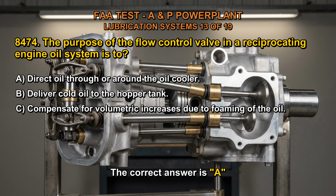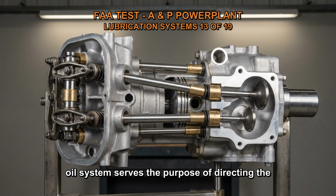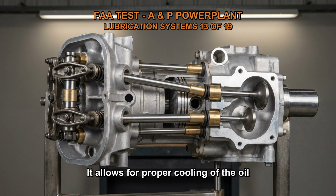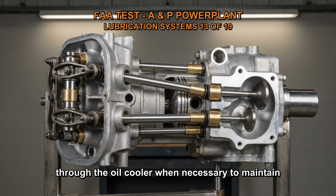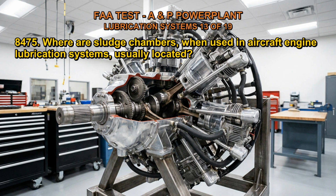The correct answer is A. The flow control valve in a reciprocating engine oil system serves the purpose of directing the flow of oil through or around the oil cooler. It allows for proper cooling of the oil by regulating its path, ensuring that it passes through the oil cooler when necessary to maintain optimal operating temperatures.